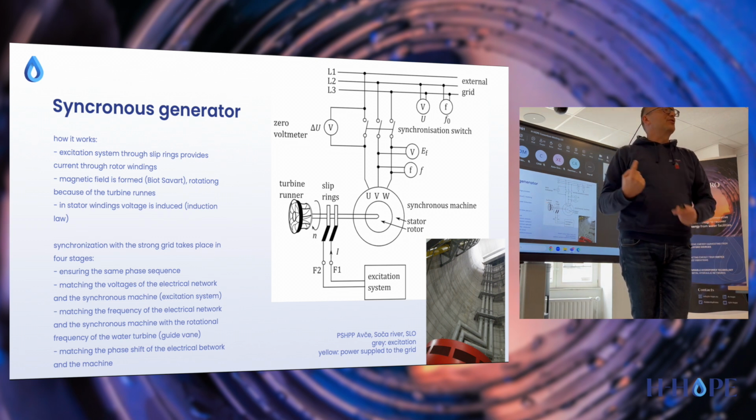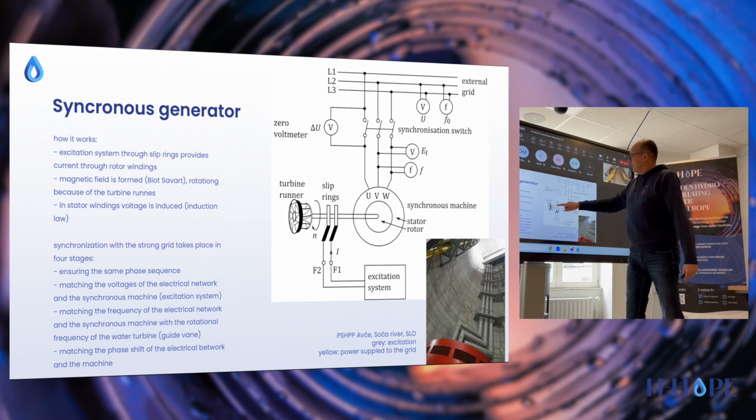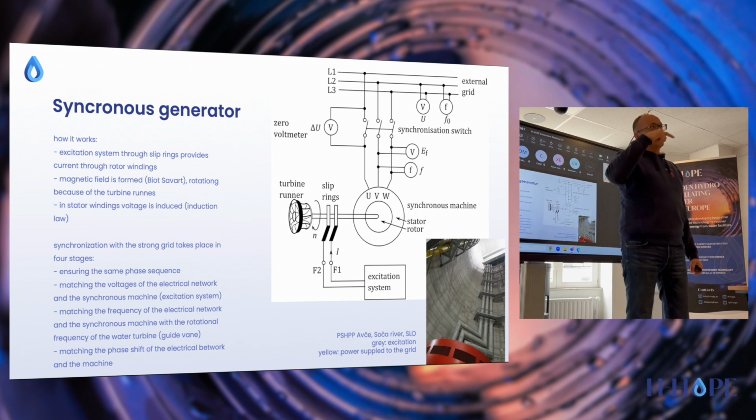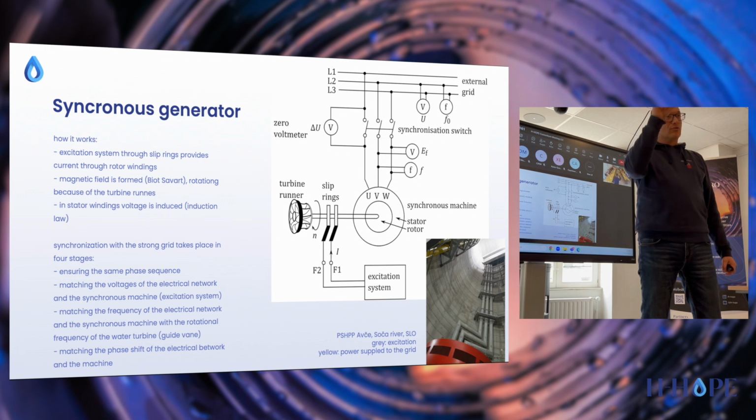That was the second equation out of 3. So let's have the turbine already in operation. It's running, and the turbine, let's say, is maintained, with variations of the flow rate of water flowing through it, so that it's running at the synchronous speed. And then you have the excitation system supplied through slip rings to the rotor, and you have the magnetic field B nicely rotating inside with synchronous speed.